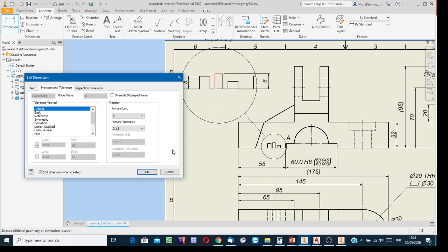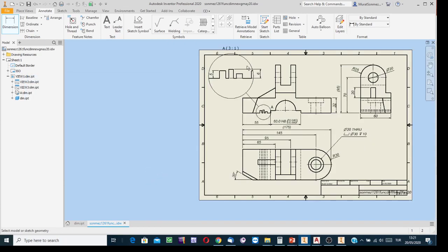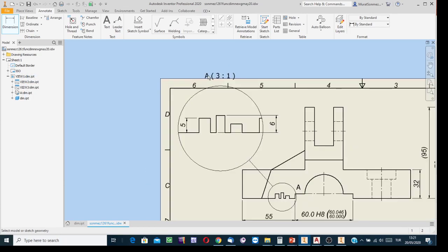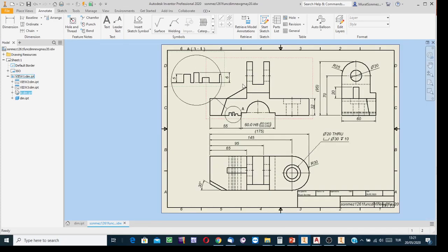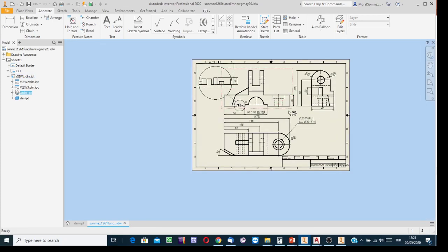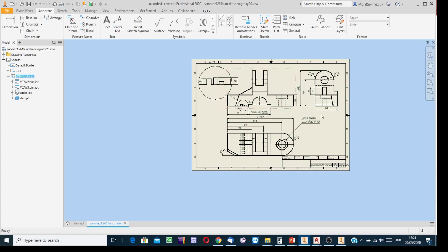Yes, and in the vicinity of this view, the same letter is written and the scale factor as well. But here the size of paper is not sufficient to fit, so try to shift the views a little bit. In such a case, to prevent a clash, it is allowable. We can unbalance the views over the paper to have more space.